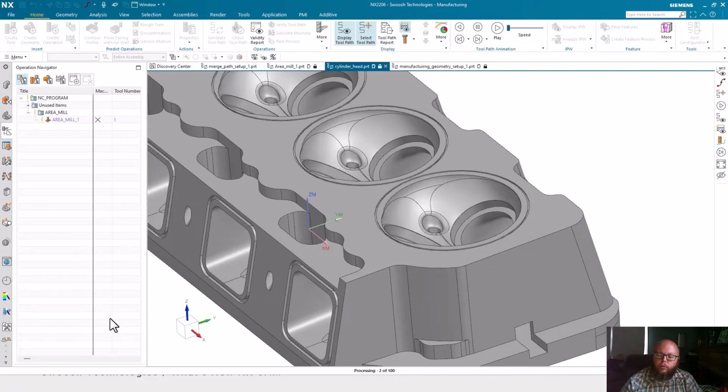It'll modify the toolpath, essentially just tilting the tool away from the part geometry to maintain any clearance values you set in that tilt tool axis function. So any regions that were colliding with the part or violating our clearance region, they're now going to be tilted away in a 5-axis motion.